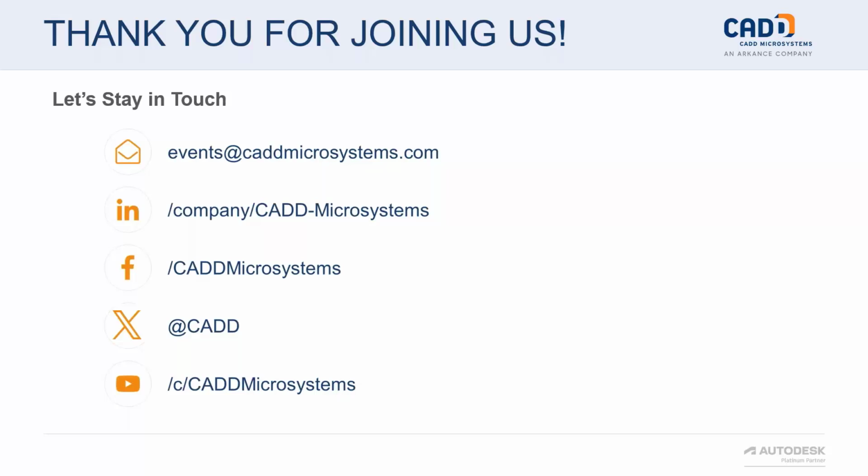Do you know? Because it feels like so much of the power and new stuff is coming from Docs. Can you use DeCap on a Docs hosted set of point clouds if you're using desktop connector or something, or is that going to get grouchy? So DeCap is going to run on the source files. So not the point clouds themselves, but say you go out and capture a site with a Faro scanner that has those FLS files. That's what you're going to be running it on. Yes, you can absolutely do it if those files are hosted in Docs, but also cached to your machine through desktop connector.